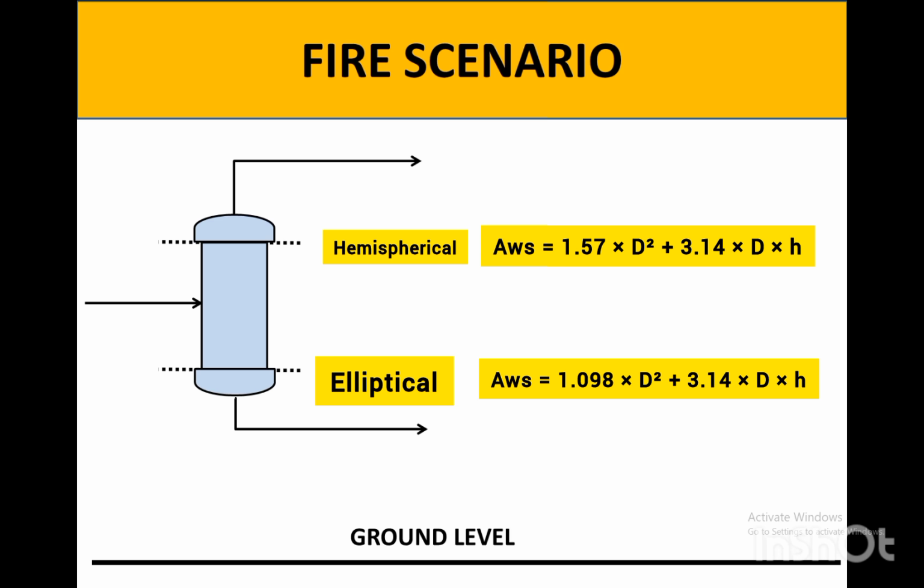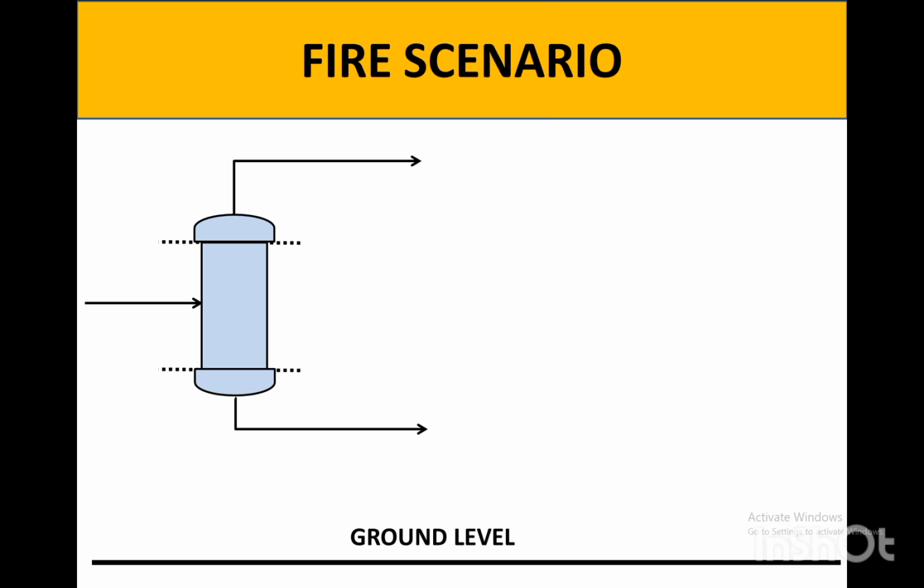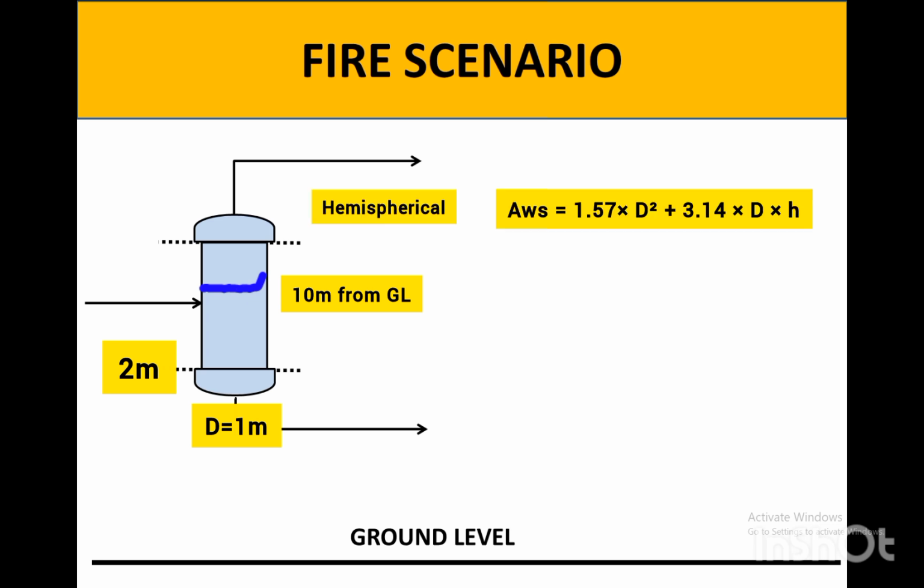Let's consider this vessel is installed 2 meter above the ground level, and the liquid level within this vessel is 10 meter from the ground level, the diameter of this vessel is 1 meter, and its head is hemispherical. So this equation is applicable.